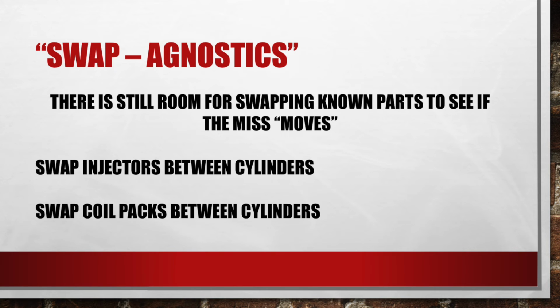Here's another tool that you can use to help you diagnose the cause of a misfire, especially if it's a single-cylinder misfire. If you suspect there's a problem with an injector, a bad injector, you verified electrically it's okay, it's getting the right power, it's got good grounds, it's being pulled to ground, but maybe there's a mechanical issue with it. Well, why don't you just swap the 2? Swap that suspect one with its neighbor that you know is okay. See if the misfire moves.